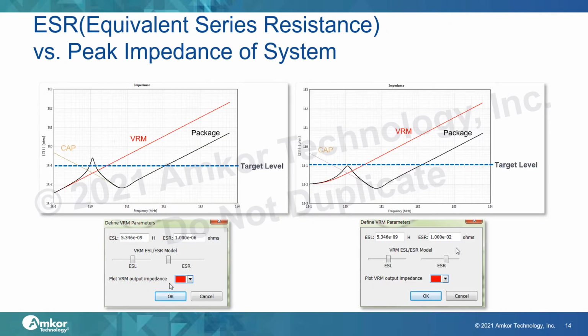The goal in power rail impedance is to push the peak frequency above the bandwidth and to reduce the impedance peak below the target level. While the subsystem module achieves the lowest spreading inductance and mounted inductance and provides a short path between capacitor and chips, the number of capacitors and their capacitance must be considered.